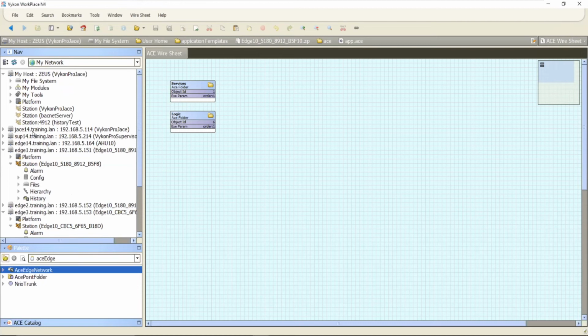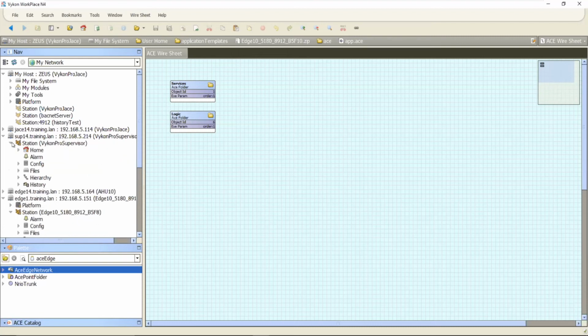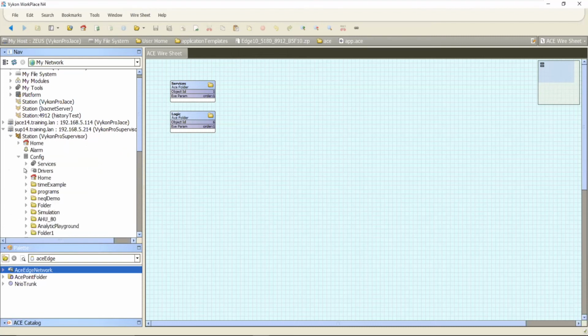All right, so the last thing I want to talk about real quickly with a few minutes I have left is what I've shown you is connecting directly to these edge controllers and one at a time going through and setting the new passphrase, changing the default platform credentials, changing the default admin account password, installing an application template or things of that nature. If you have multiple devices that you want to deploy, then one of the things that you can do is utilize provisioning.